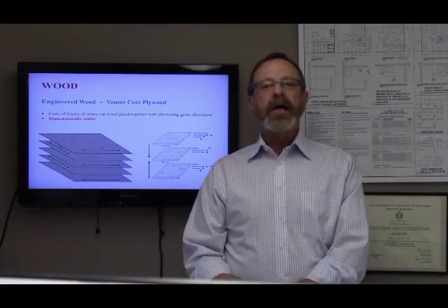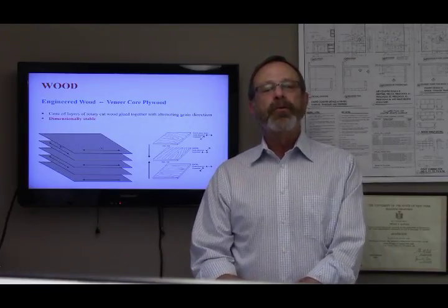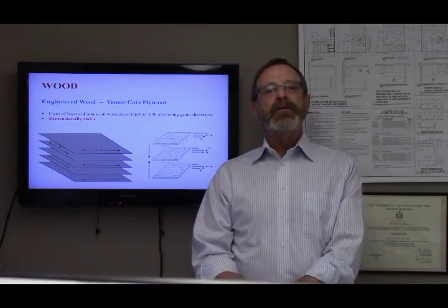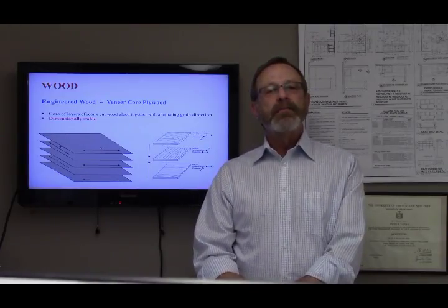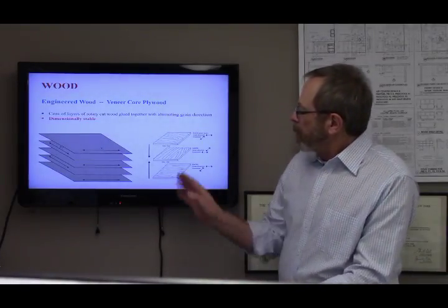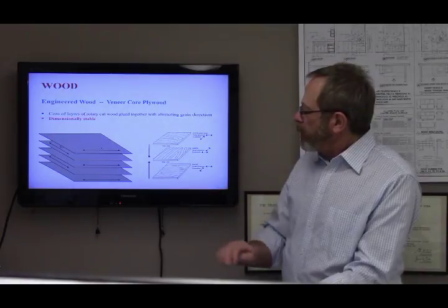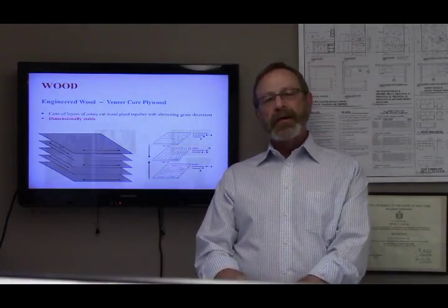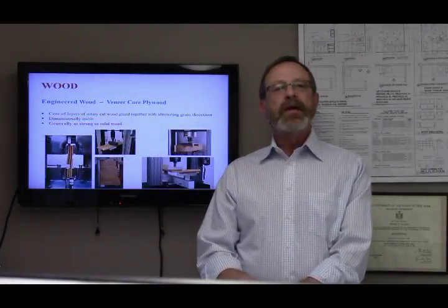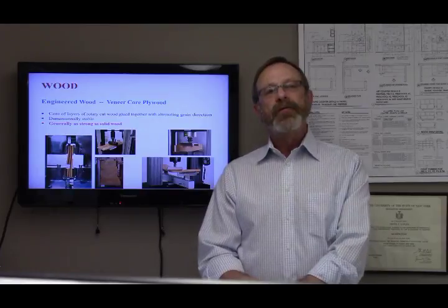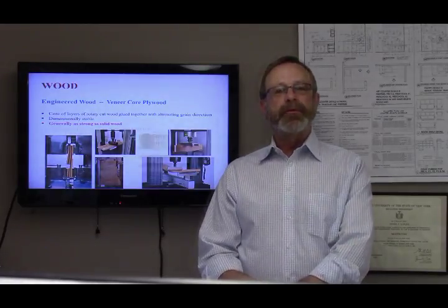The layers in plywood are aligned according to a predetermined arrangement, so as to obtain equivalence of its properties of stiffness and strength in the main directions of the board. Here you can see the alternating of the individual veneers in directions that will benefit the final board. In cross-lamination and gluing of plywood, capitalize on the wood's most desirable physical and mechanical properties.